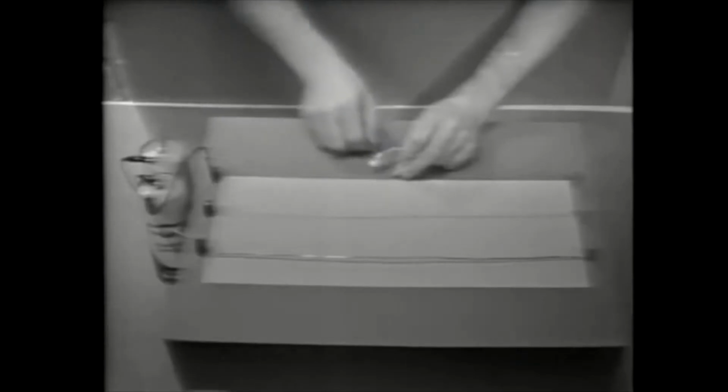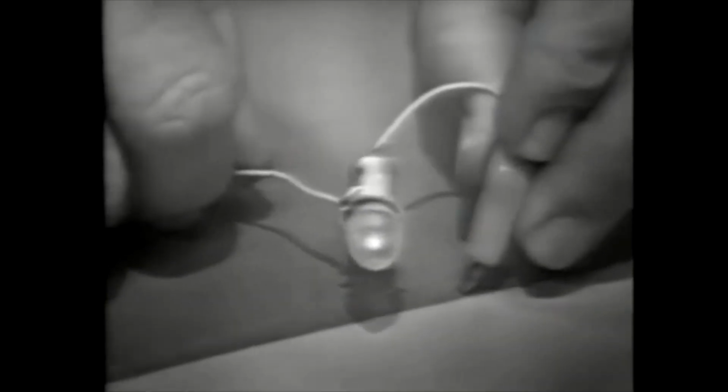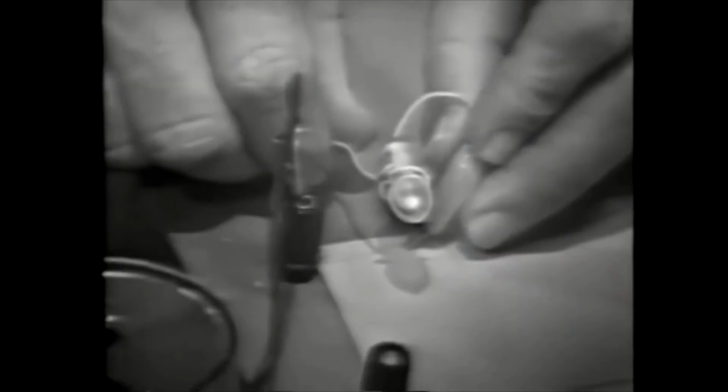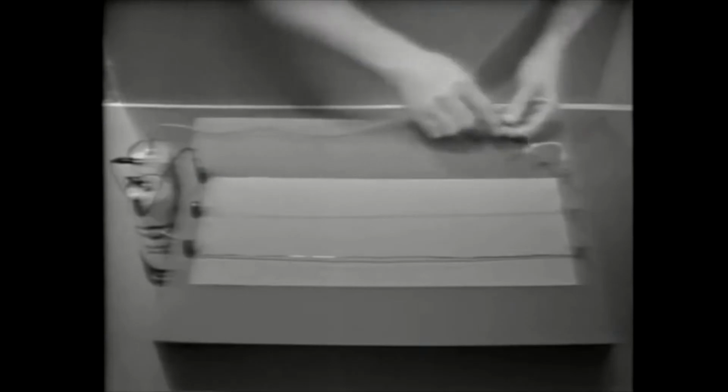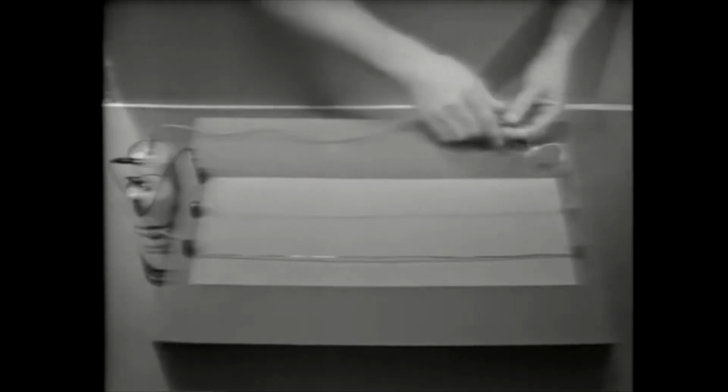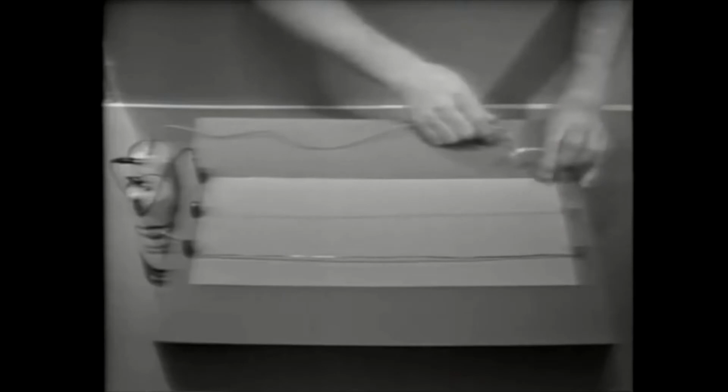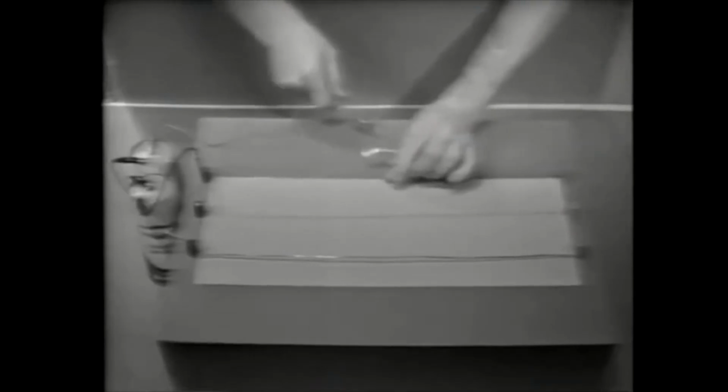Well, let's go on down to the end of the wire. Watch the bulb. As I decrease length, I decrease resistance because the bulb is glowing more. Well, this is pretty obvious. Let's take a look at it. When I had the bulb over here, the electrons had to travel the full length of this resistance material. So it's only natural that it's going to encounter more opposition. But as I decreased the length, I decreased resistance, and the bulb glows brighter.